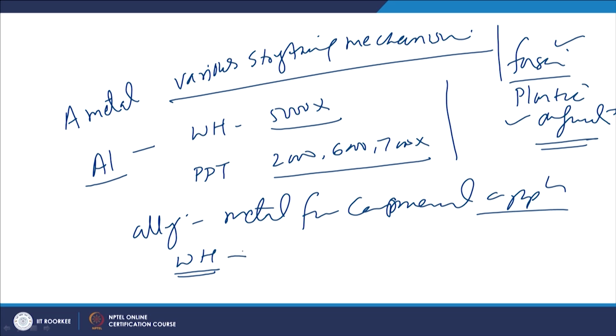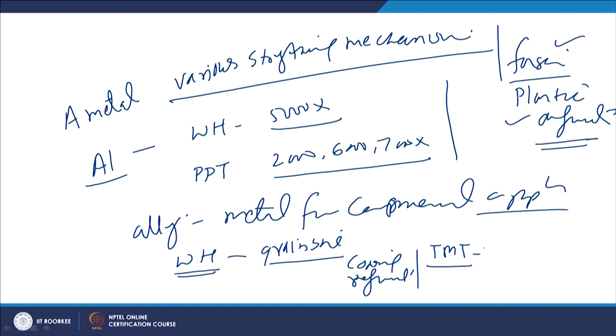Whenever there is work hardening or controlled thermal cycle application during manufacturing, there will be grain size variation. There may be coarsening or refinement of the grains. For example, the low cooling rate experienced during casting leads to a coarse structure, while the higher cooling rate experienced in the weld metal during welding leads to a fine grain structure. In the case of thermomechanical treatment, refinement of the grain structure is achieved. Apart from grain refinement, in some steels strengthening is realized through the formation of precipitates. So, it is also possible that the metal has the effect of some precipitates or some phases realized through controlled phase transformation.